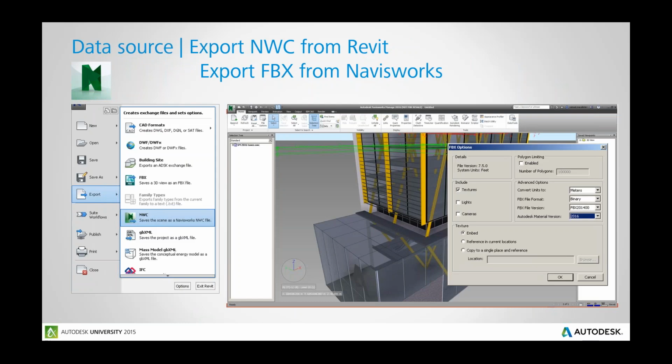And as mentioned before in the covering slide, if you don't have the file formats to open inside of Revit, if you've got numerous file formats that you want to try and open and convert and test, you can open it up in Navisworks, and Navisworks will allow you to export out as an FBX. So there's a number of tools here as well for you to maybe work with a heavy model. So let's say for example, you got that 1 gigabyte Revit model and it's absolutely huge. Navisworks is a great application for you to open that model.